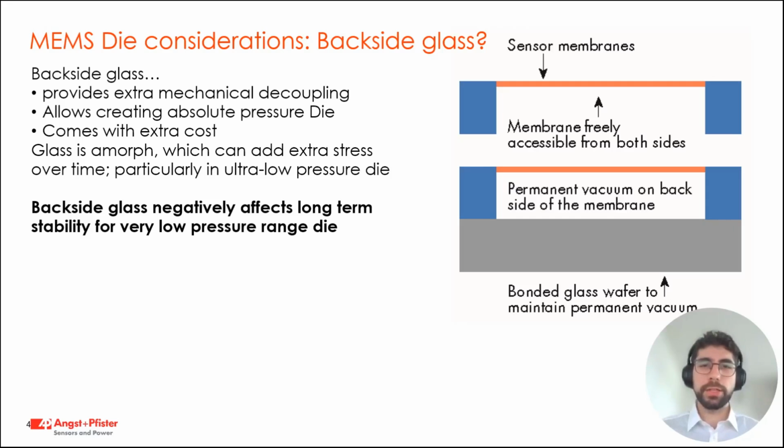With higher pressure sensors, it is enough to, for example, shut down the tool where the sensor is measuring some sort of process parameter. Even with the tool shut off, there is always some pressure difference of up to a few Pascal or even millibar, but this can be considered zero for higher pressure sensors. For low pressure sensors, however, this may equate to the entire measuring range.